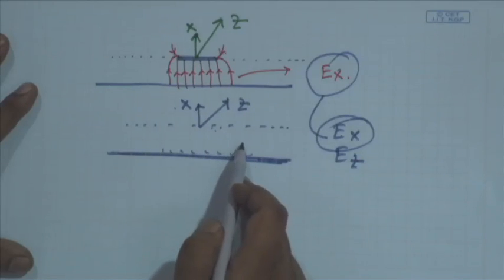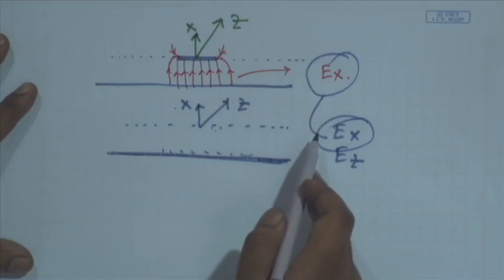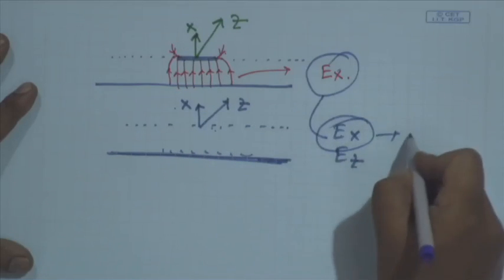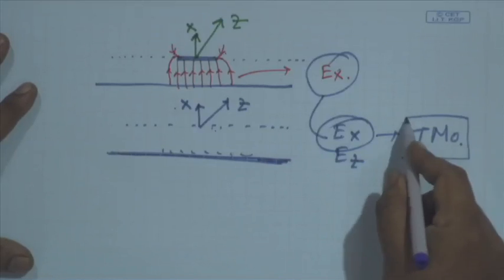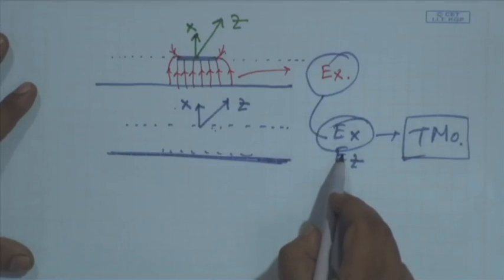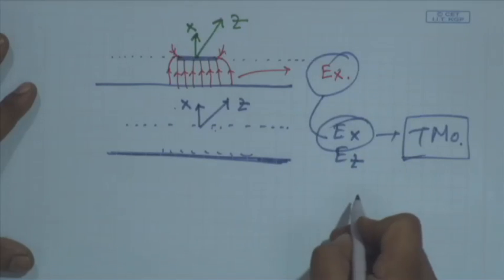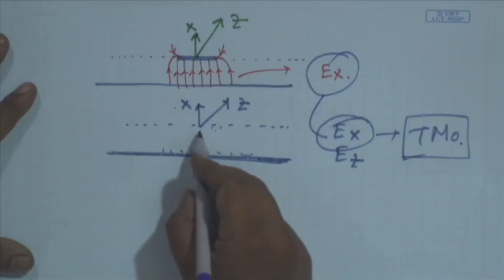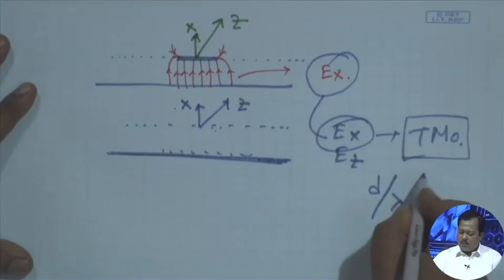So, in fact, the microstrip line always excites this surface wave, which is given as TM0 mode, which has no cutoff frequency, and the power lost to this surface wave actually increases. It is a function of thickness with respect to lambda or lambda g.